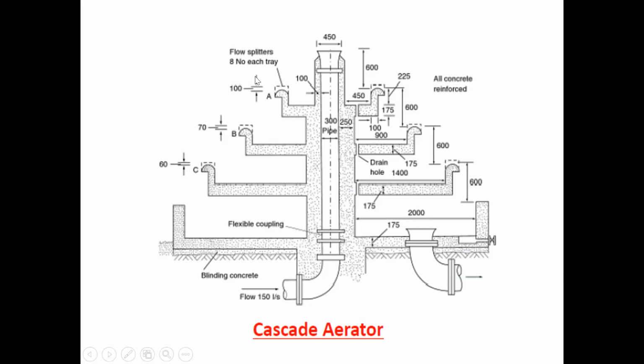You can see the height. So this is the height when water is passed over this, which may be 1 to 3 meter. Okay, so you can see 0.6 meter altitude or height is present in this; it completely depends upon the quantity of water coming. We have to analyze the assessment of flow discharge coming, and what amount of impurity is present in that. Depending on that, we have to decide the altitude and design those steps. Okay, so design of cascade aerator, you also have to know how design is carried out. We'll discuss that part later on.